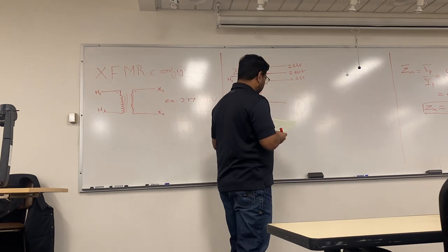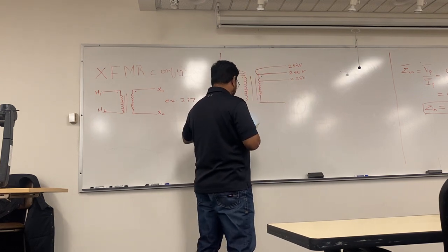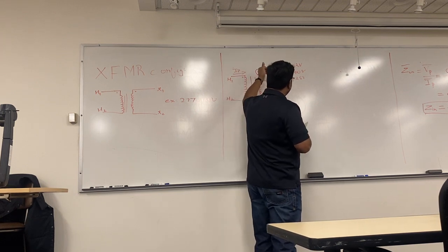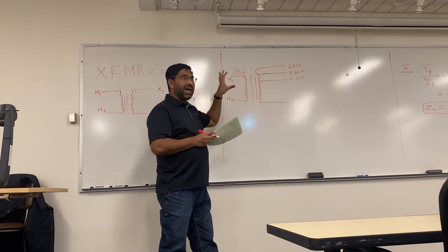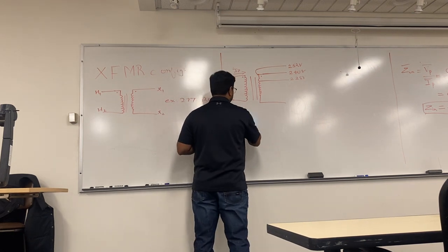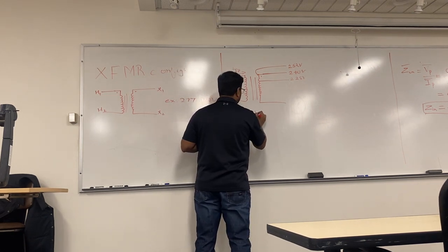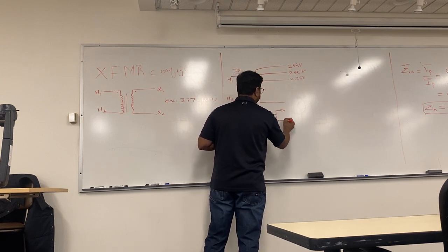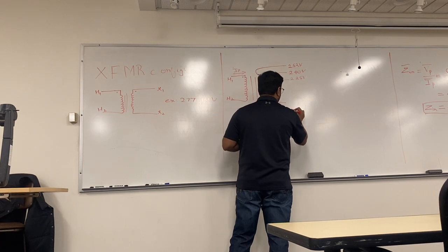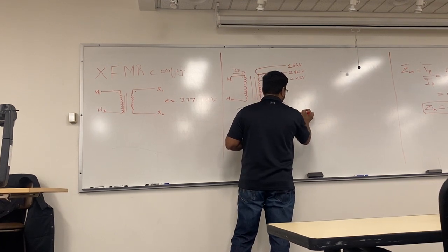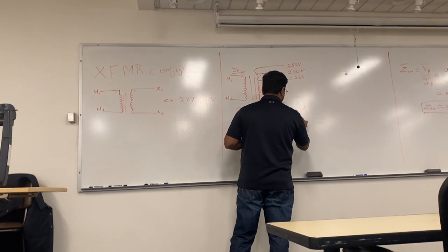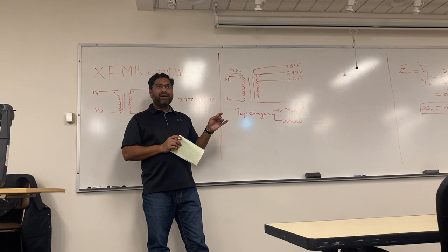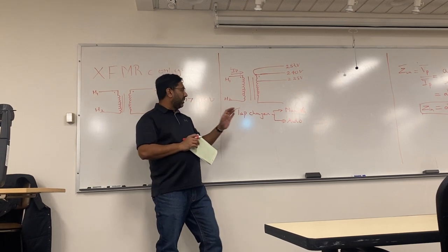So this should be your first example, so to say, where you're seeing that, hey, I'm able to tap up and tap down. And there's literally an equipment called a tap changer that does this for you. Could be manual or auto. If you have an understanding for the load, you would always set it in auto.